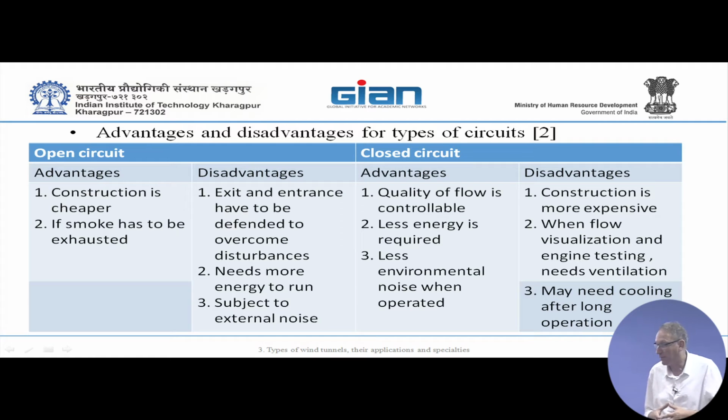And when you make a flow visualization, you'll have to stop sometime because it will be congested and you will not see anything. Everything will be smoggy. And also, all the alarms will start and operate in the building because you have some material that disturbs the sensors. And it happened, I'm telling you. In the wind tunnel in Tel Aviv, we were doing this. I was insisting to have a closed circuit one. We started to make some visualizations, and we didn't care about the alarm sensors. And at that point, the whole building was crazy. All the building was in alarm.